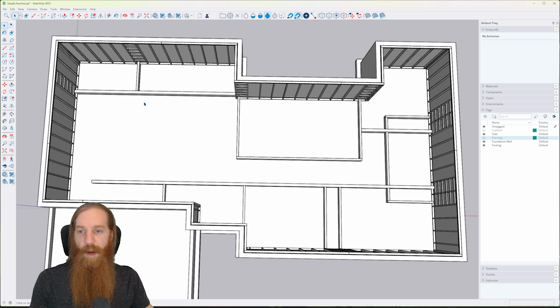So our load-bearing walls for the joists above are going to be right here and right here, okay? And then also this little wall right here will be load bearing as well. So those are all going to be 2x6 framing. All the other walls are going to be 2x4 framing. Very simple and easy to do. They're all going to be 24-inch on center stud framing.